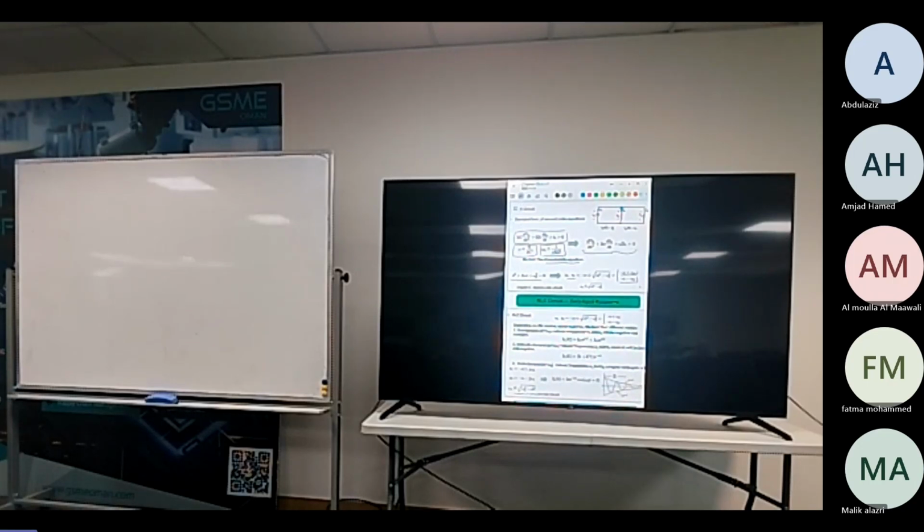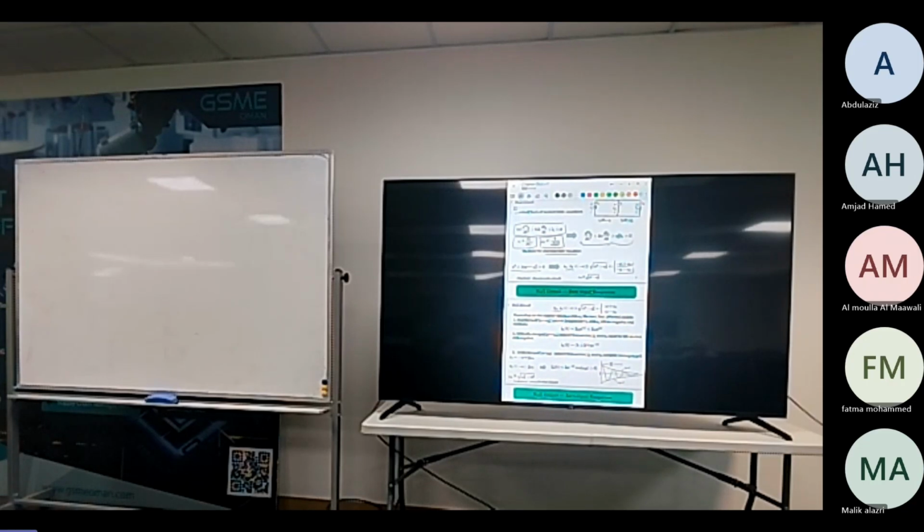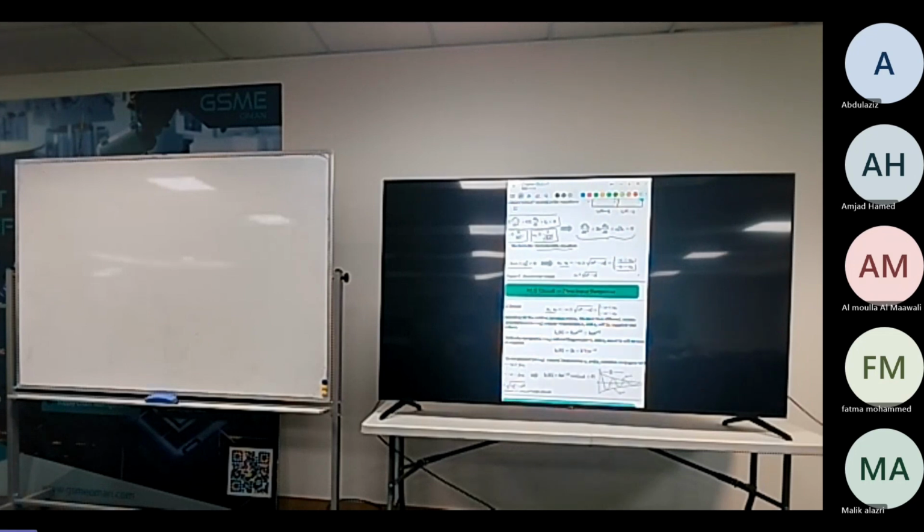If we solve it, we will have three different responses. The first one, S1 and S2 both are real. In the circuit, both of them should be real and negative. They cannot be positive, because the response should decay, which means as t approaches infinity, this value should go to 0. It cannot increase, unless we have positive feedback, which we will see in electronics.